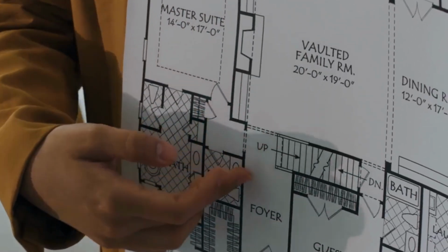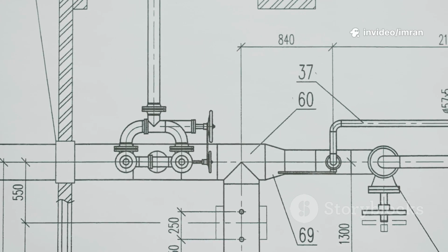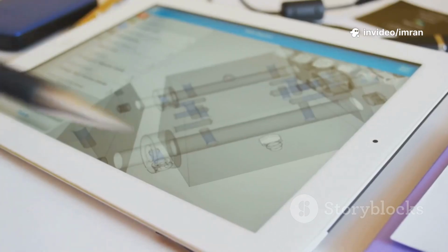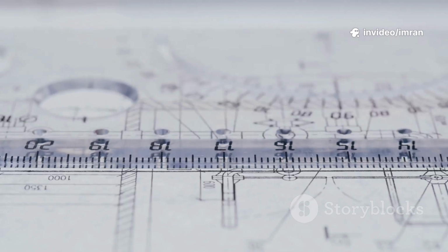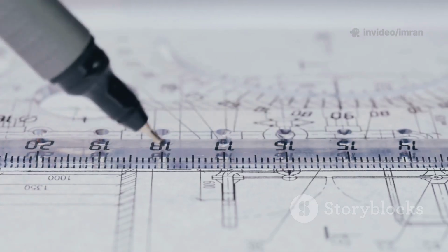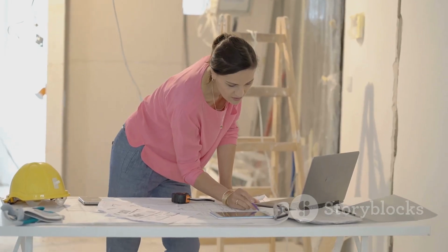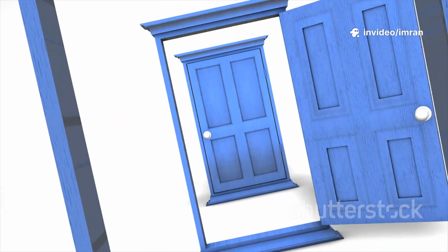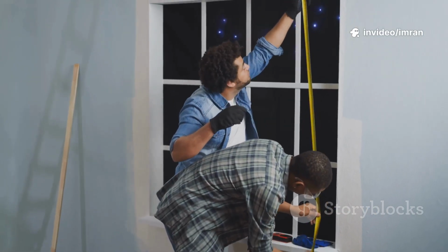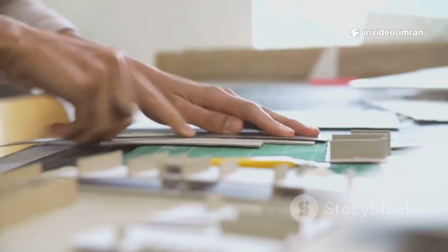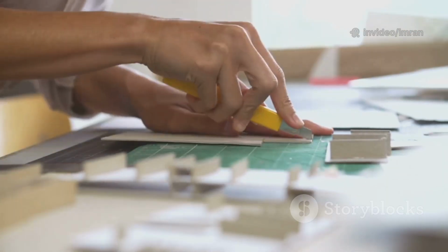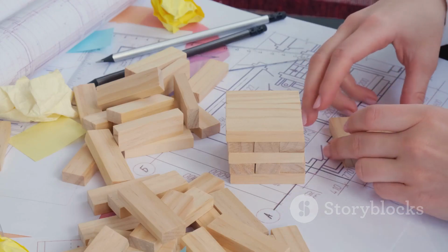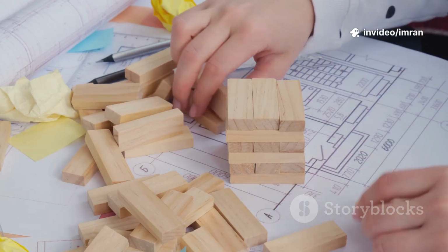Our room will be a simple rectangle measuring 5,000 millimeters in length by 4,000 millimeters in width. We will be drawing at a 1:1 scale in model space, which means one drawing unit will represent 1 millimeter. The walls will have a thickness of 150 millimeters. The door will be a standard 900 millimeter wide door, and the window will be 1,200 millimeters wide. Having these key dimensions decided before we begin will make the drawing process much smoother and more accurate. This planning stage is a crucial part of any design project.